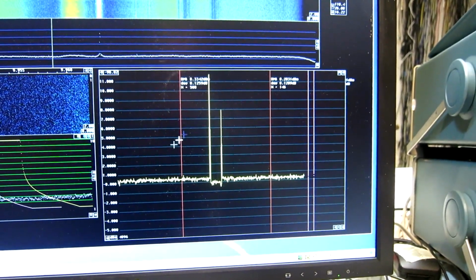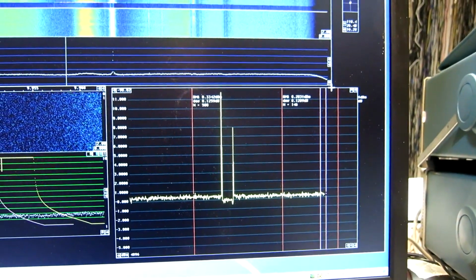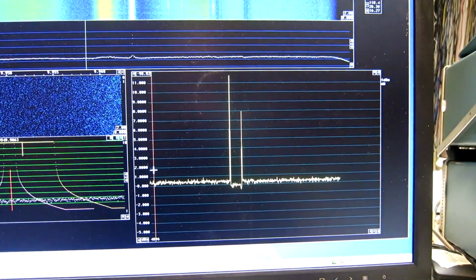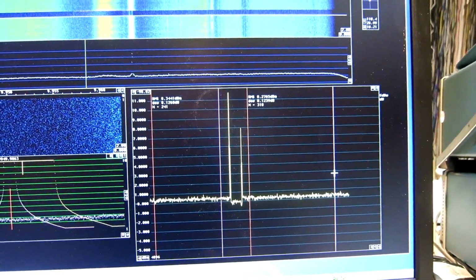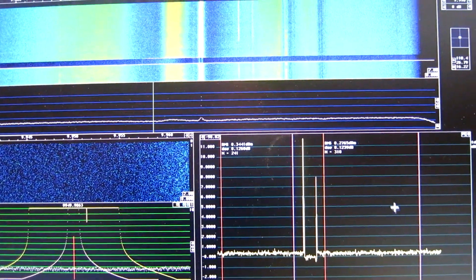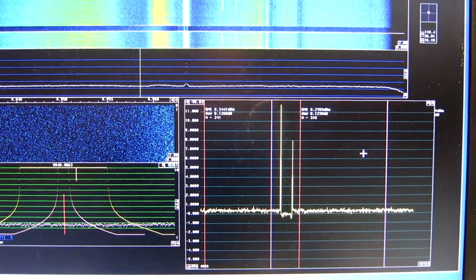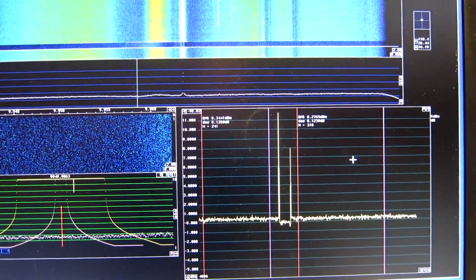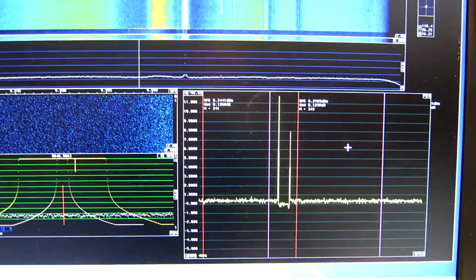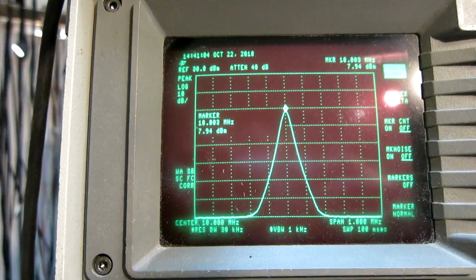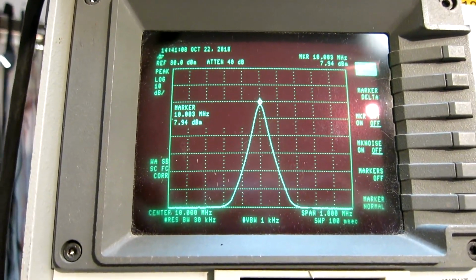I can do, well, I clear screen again and look at the capacitor and the straight-through wire, and then there's a difference of 0.05 dB, which means that the noise is far below the minus 205 dBc per hertz. That is the limitation of this test system. The level on the coupler is 7.9 dBm.